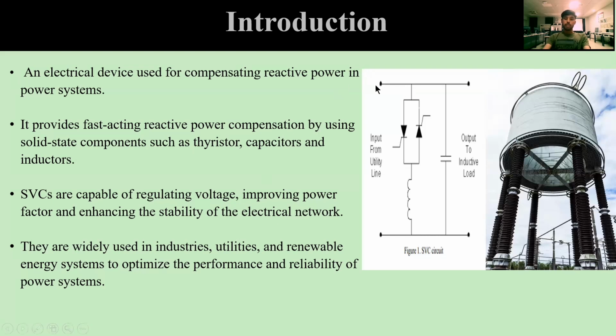This line shows a transmission line, which is delivering power to the load, or we can say it's a bus. In parallel, we have connected our shunt device, the static VAR compensator. Whenever we need lagging VARs or leading VARs, we can provide both of them through these capacitor banks and through this controlled reactor.